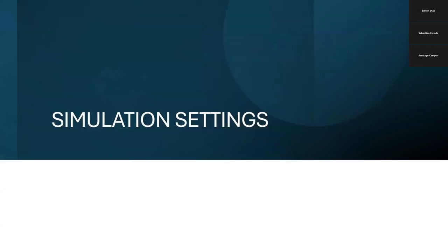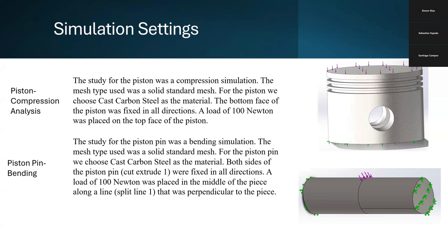These are simulation settings. The study for the piston was a compression simulation. The mesh type used was a solid standard mesh. For the piston, we chose cast carbon steel as the material. The bottom face of the piston was fixed in all directions. A load of 100 Newton was placed on the top face of the piston.